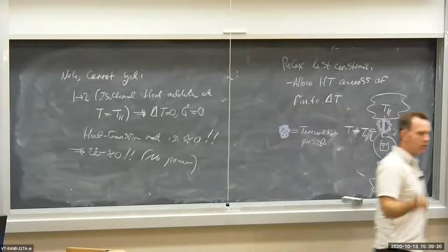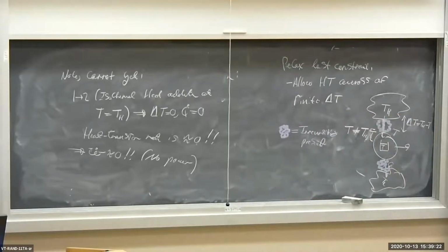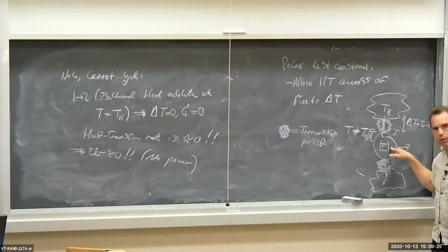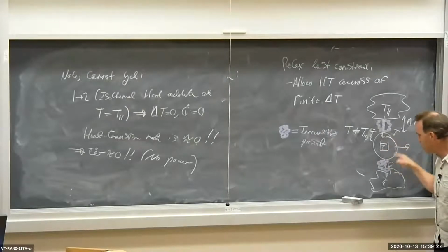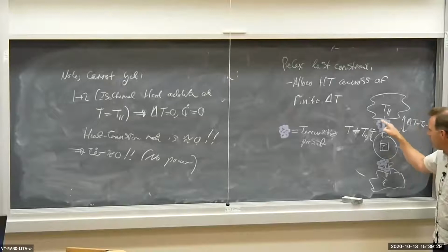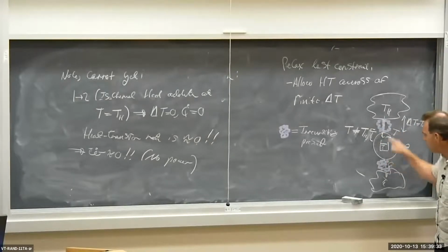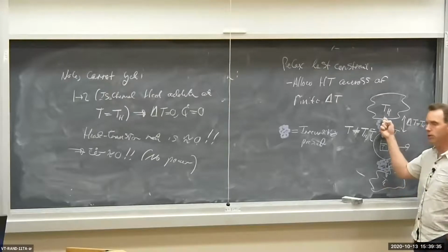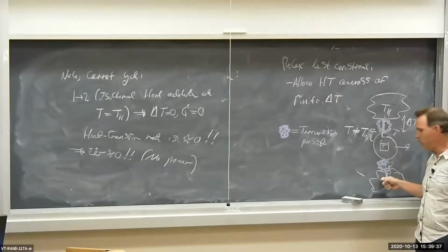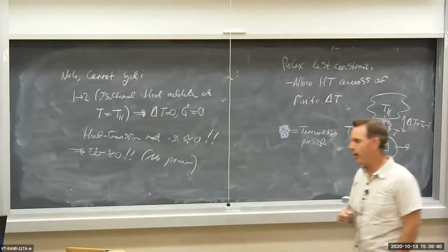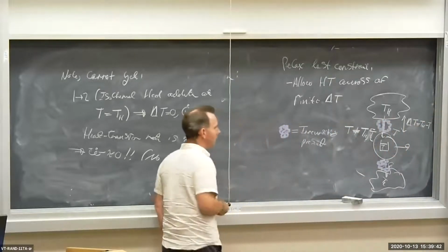In other words, the cycle that we're going to analyze is internally reversible. There's no irreversibilities going on inside, but there are external irreversibilities. There's irreversibilities occurring between the source of the heat, which is the high or the low temperature reservoir, and where it interacts with the system, which is at a temperature T.